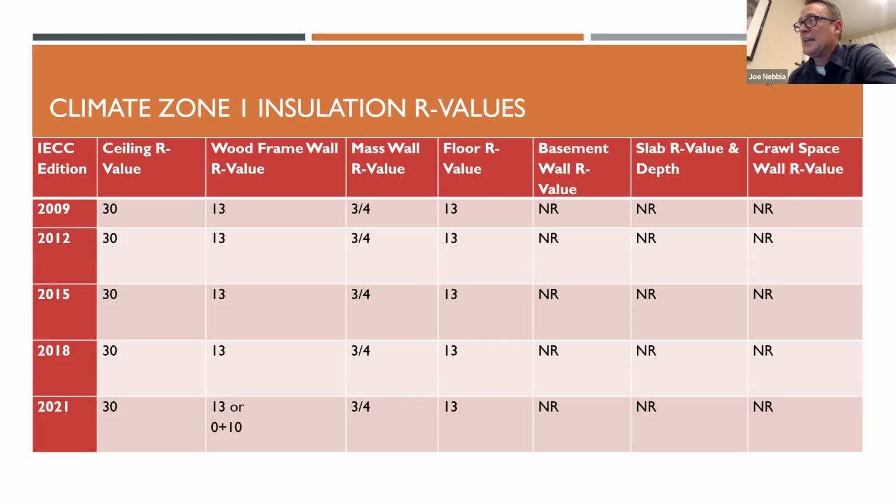Foundation insulation can get a little bit tricky sometimes with termite issues, and you have higher termite incident areas as we get further south. So that's something to consider. So it will certainly improve the efficiency of your structure if you do insulate the foundation, but it's not required according to code. Where we do have requirements is in the ceiling, wall, and floor.